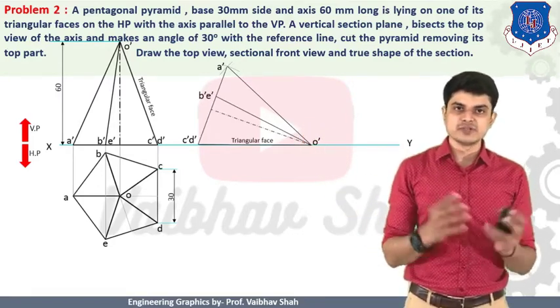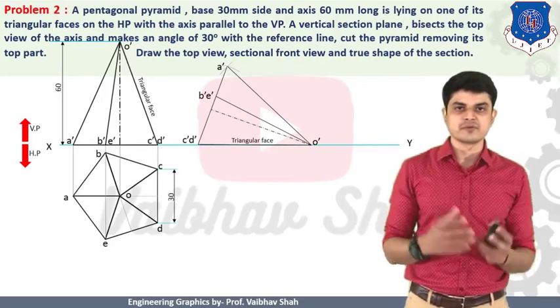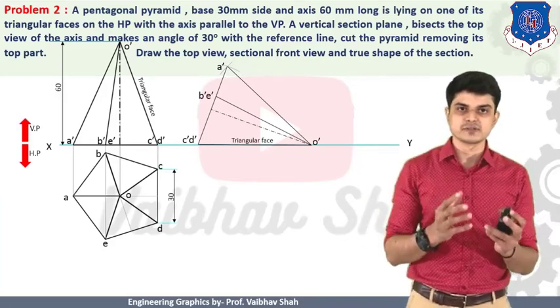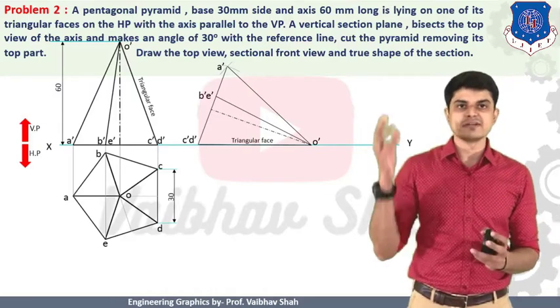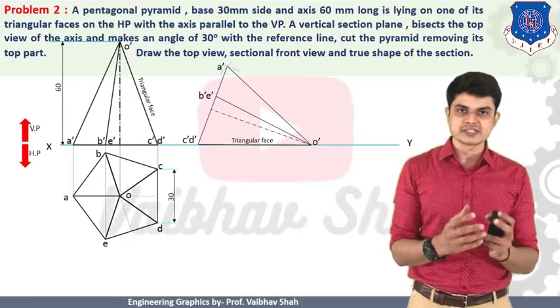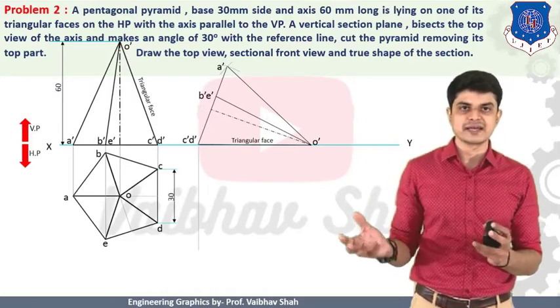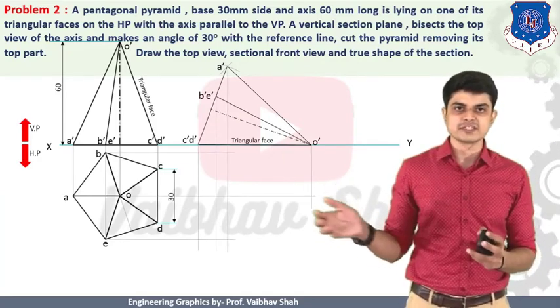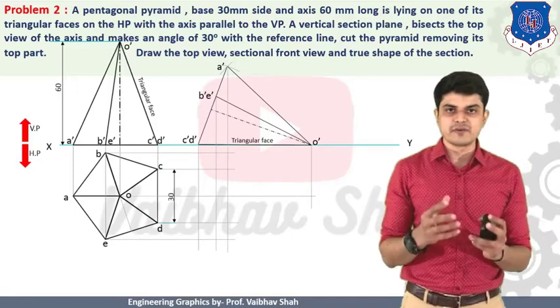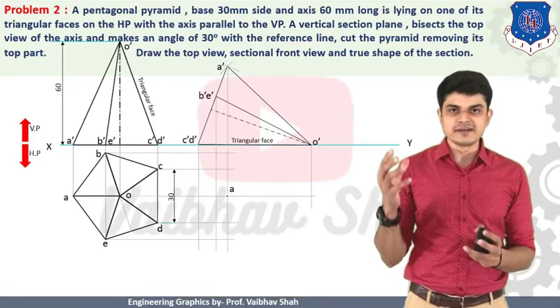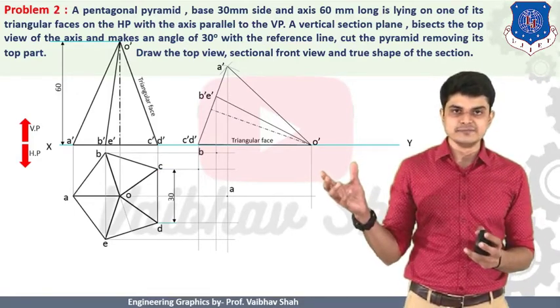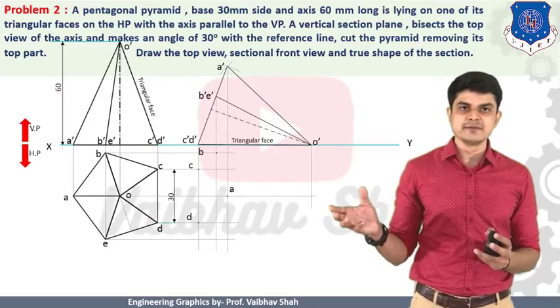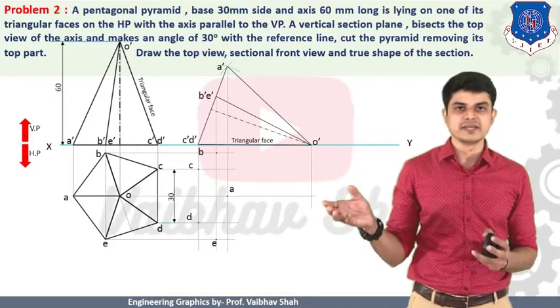After getting this object, we should finally draw its top view from the top direction. So let us observe this object from the top direction. When we observe the object from the top direction, we can have vertical lines of projection like this from each of the points, as you can see, and horizontal lines from the previous points. And then we should define the points of intersection like A, B, C, D, E. And then finally we will be defining your apex point somewhere here.